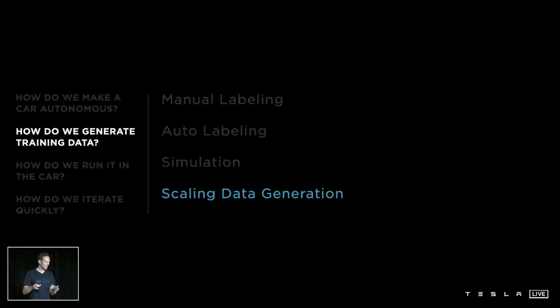In the specific context of the push we went through as a team a few months ago to get rid of the dependency on the radar sensor for autopilot, we generated over 10 billion labels across 2.5 million clips. To do that, we had to scale our huge offline neural networks and our simulation engine across thousands of GPUs and just a little bit shy of 20,000 CPU cores. On top of that, we also included over 2,000 actual autopilot full self-driving computers in the loop with our simulation engine. And that's our smallest compute cluster.